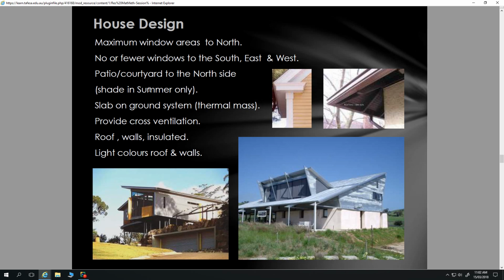Thermal mass can be a benefit or a curse, depending whether it's used correctly. When used in conjunction with proper orientation, getting lots of sun onto that concrete slab during winter, and then no sun on that slab during summer, that thermal mass is being used very well.